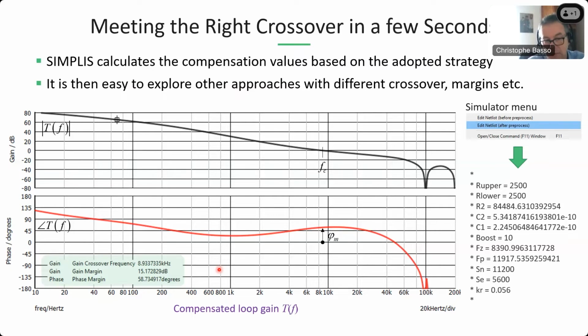So once again, it's important to test the power supply with a very basic op-amp model, and then once you have what you expect, you replace the very basic model with a more comprehensive model, including, if possible, the DC gain and the low frequency and high frequency poles, and you will see how they affect your transfer function. If you want to push the exercise further, you can include different things like slew rate, and check the effect of a transient step to make sure that the slew rate, for instance, is not going to affect the large signal response.